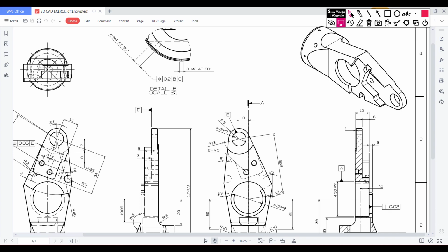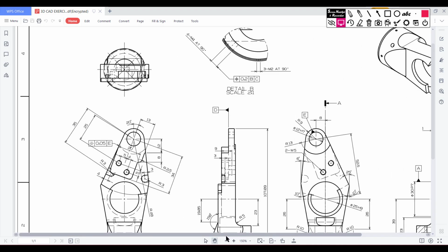So in our sketch we have drawn this portion. Now it's time for drawing this cut. How will we draw it? For drawing this cut, we can see we have to first draw a circular profile of 3 radius, and it has a distance of 4 unit and 35 unit.